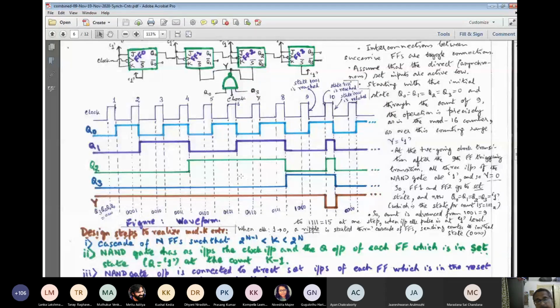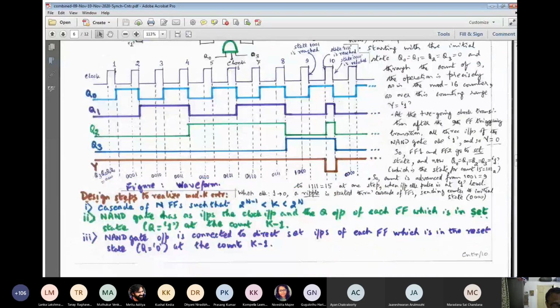If you design a 12-bit or 16-bit counter fully synchronous, then the clock signal will have to feed no less than 16 flip-flops, and that can lead to a strain on the loading ability of the clock driver, right? So we can always augment the design based on the need. But as far as I can see, there is not much critical need in keeping the clock with a particular specified duty cycle. That is as far as my knowledge goes.